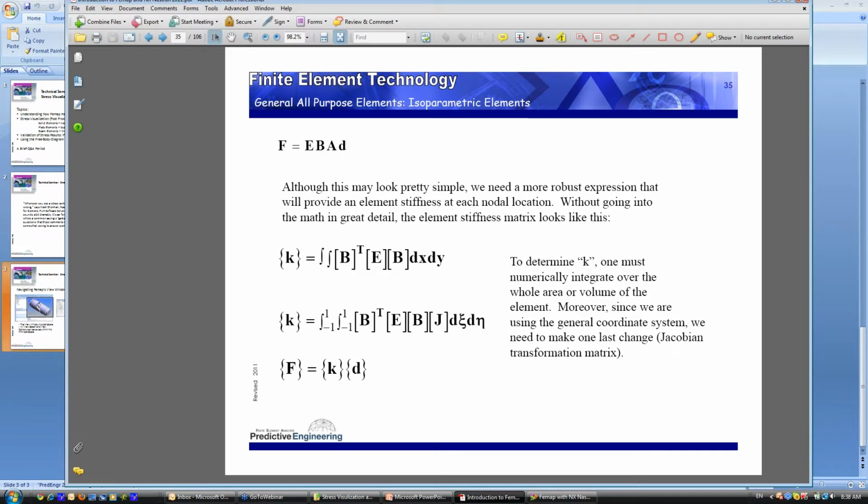So what they decided many, many years ago is that let's go ahead and normalize it into the -1, +1 coordinate system. And this normalization matrix is going to be a Jacobian. Right there. That's the term J. And for you guys who have been out there in the FE world, you've probably seen the Jacobian bantered about, wondered maybe exactly what it is, what it's doing. All it is, it's a transformation matrix. It's a linear transformation matrix. Think of what's a transformation matrix? It's like, okay, y equals A times x. A is your transformation matrix for one scalar. So if A is 2 and x is 1, then your y is 2. If A is 3, then your y is 3. Given the value of x is 1. So it's just a transformation matrix, and it tells you how much work it has to do to transform from dx dy into this normalized coordinate system.